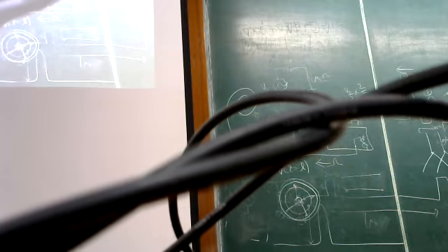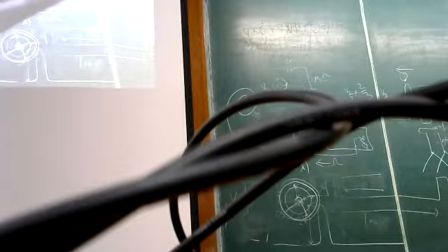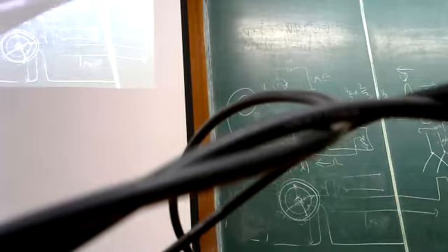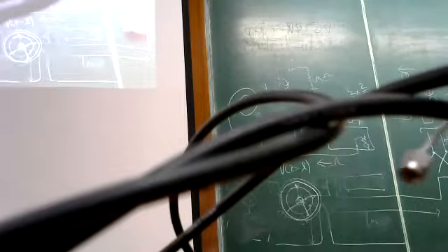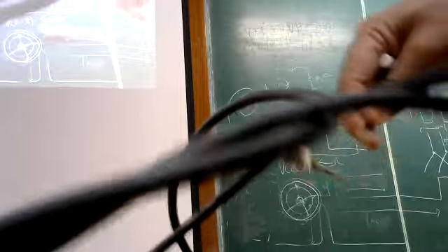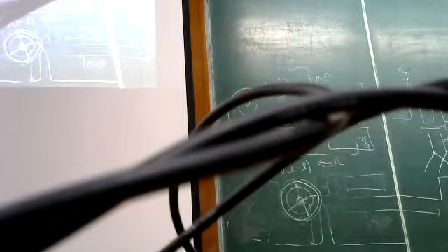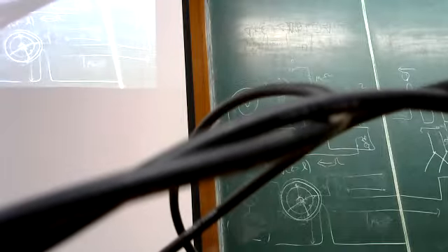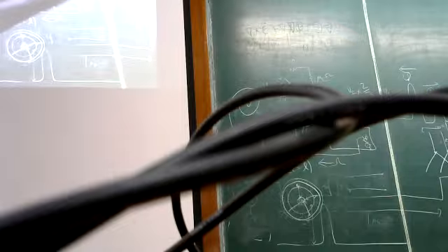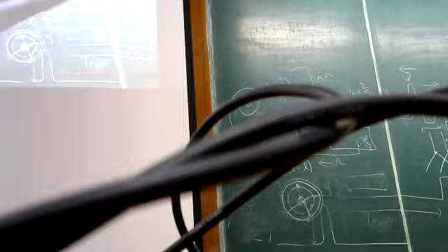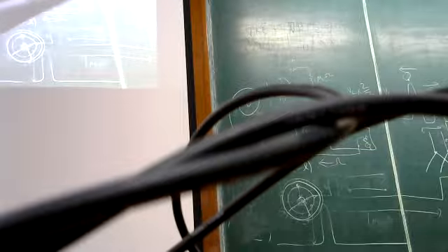Right? It's bigger. The outside diameter is bigger, and you saw there's also this white dielectric in the middle, and there's a center pin. But the characteristic impedance of this connector has to be the same as the characteristic impedance of the cable. So by using different choices of the dimensions, you've made a larger connector, because you can imagine that if I had a connector which was the same diameter as this one, it would be very hard to work with.